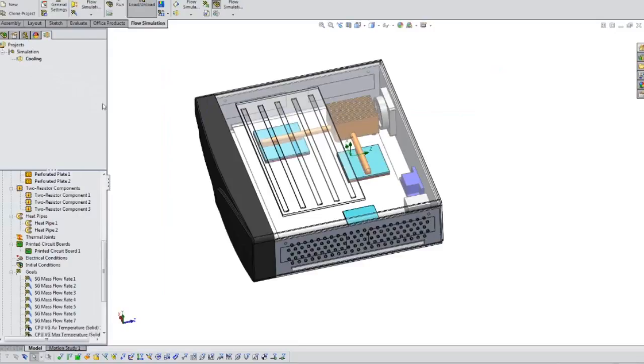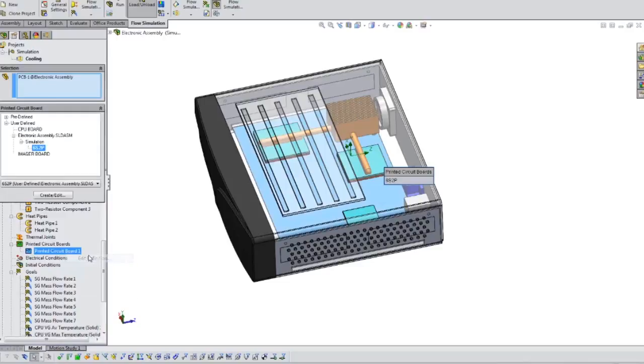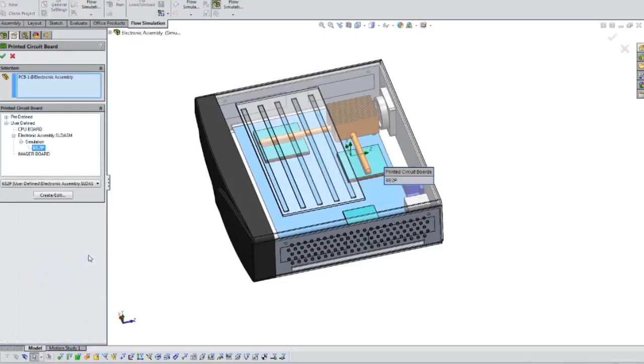The next thing we do is we can come in here and turn on SolidWorks Flow Simulation. For anybody using network licenses, just remember, the left-hand side turns on SolidWorks Flow Simulation for this session only. The right-hand side turns it on for every session. So if you're turning it on for every session, you're always going to be pulling that Flow Simulation license. You might have a guy knocking on your door asking you why you're using it when they may need to use it.